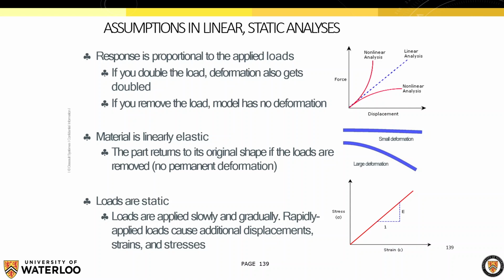So some of the assumptions in linear and static analysis, this is what we're going to be doing today in the demo in about 5 minutes. But a linear analysis means that when you apply a force, you get a displacement. If you double the force, you get double the displacement. The response is linearly proportional to the input. That's what it means. Okay.